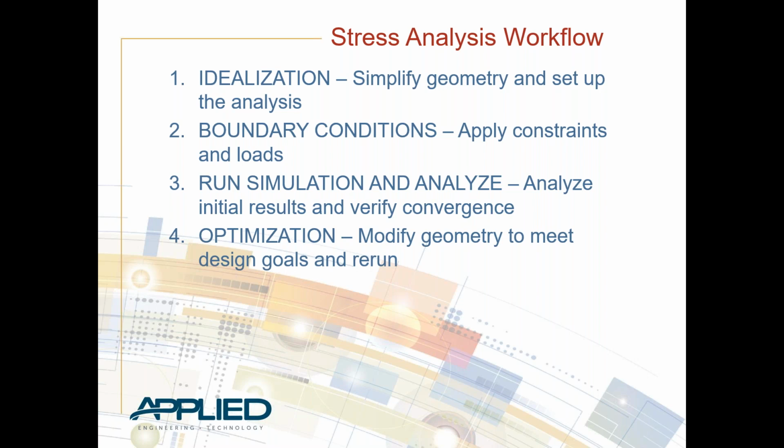And then we've got the solid elements, for when you've got castings with different curvature and multiple different thicknesses throughout. From the types of products that I work on, the solid element is typically the most common. But if you're doing a lot of sheet metal, then shell can be an even more accurate way to run an analysis. So keep those in mind. If it's an assembly, you might have some solids and some shells, and you can have those work together in the same analysis.